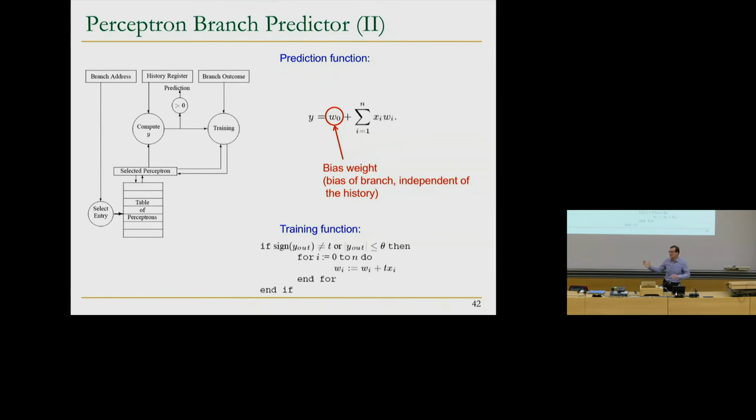So in this case, this is a single layer network, so backpropagation is limited to this algorithm. But if you actually do more sophisticated learning, yes, you need to implement it in hardware also. Maybe for branch prediction the latency is too long, but people actually design hardware to do backpropagation today. Very sophisticated hardware. Google's TPU is one example. Recently, Tesla announced their own chip to do inference for learning, and they do all of that in hardware also. But branch prediction may not be a good application for that because the latency requirements are very low, right?